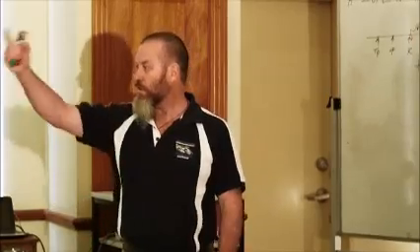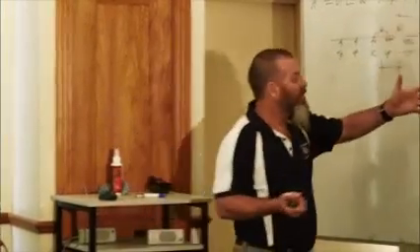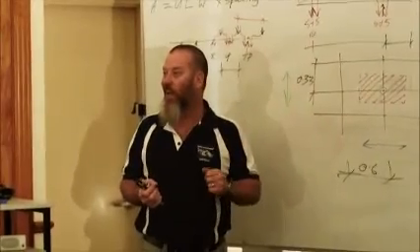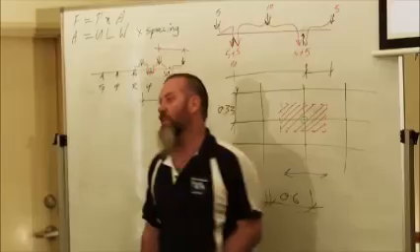So when you're doing an assessment of a connection, the first step you take is you look at it and you say, is this an outside wall connection? Yes or no? Simple as that. Is a lintel plate an outside wall connection? Yes. So the formula I use is DBC divided by 2 plus the overhang. Okay, that's basically how you do it. Is a batten rafter an outside wall connection? No.